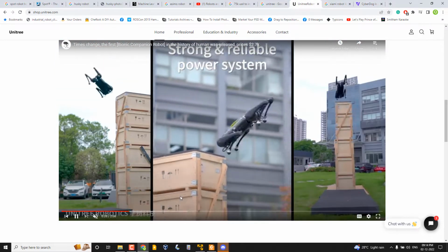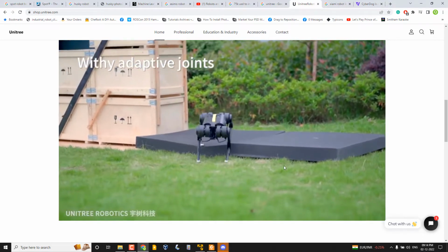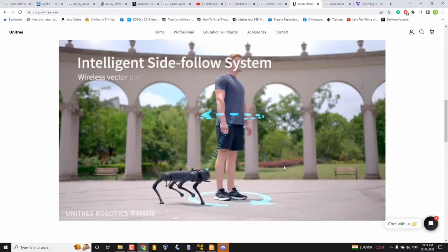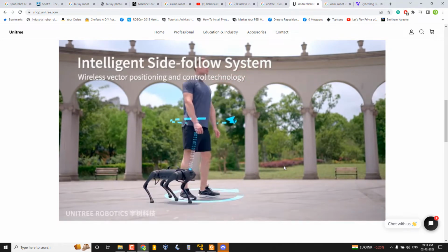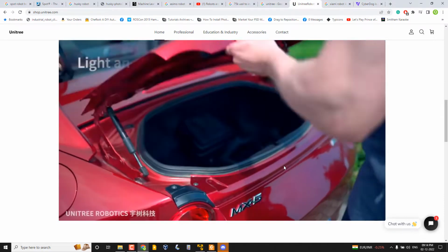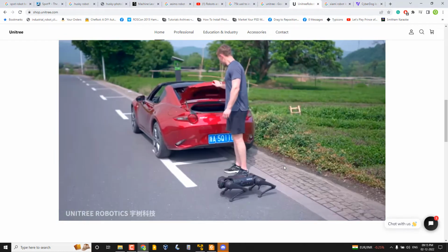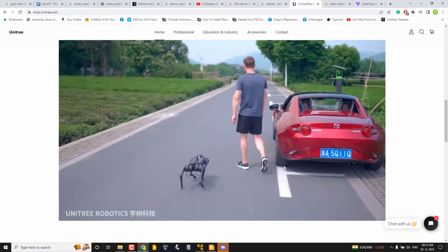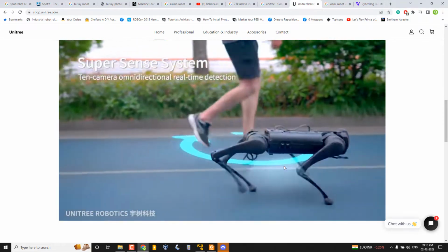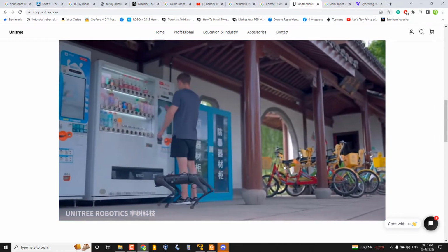Tejas is having a question: how does the kinematics differ from differential drive? So Tejas, differential drive basically adjusts the speed of two wheels. It can be two wheels or four wheels, but basically the logic is that if the two wheels have the same speed, it will go forward and then backward. Here, instead of adjusting the wheel velocity, it has gaits.